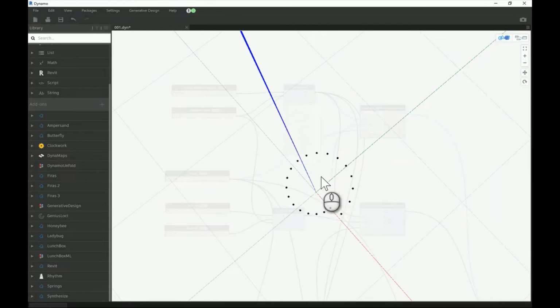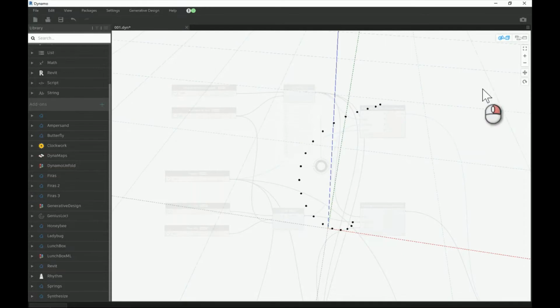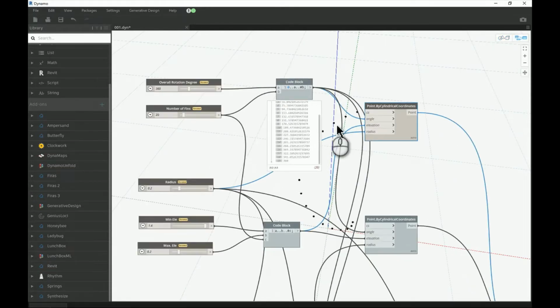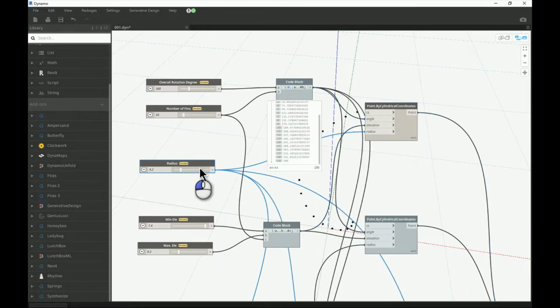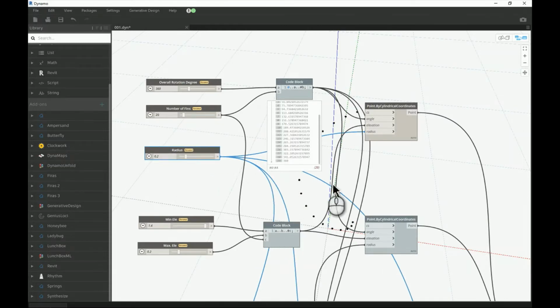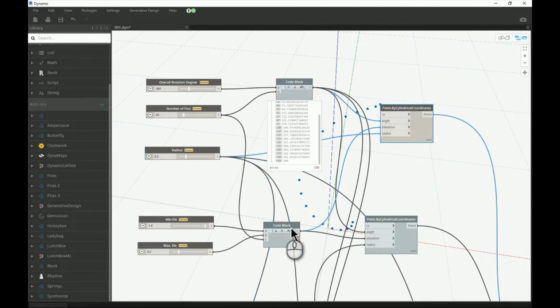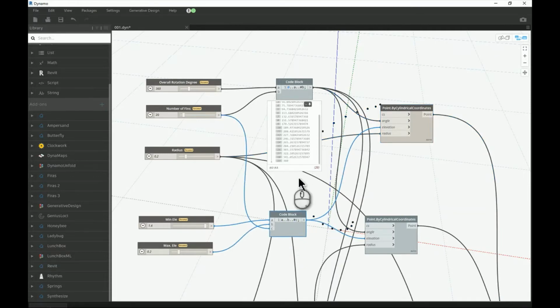Now the other things to specify for that spiral or helix, whatever you want to call it, are the elevation and the radius of it. The radius is fixed here, not changed, set to 0.2 for all the points at the same value. That's a fixed value here and not a range. And the elevation is actually changing to provide this spiral shape. Again, it starts from A, which I didn't set to 0, so you get more options. If you put 0 like what you've done, you're going to start from 0, but you're going to have less options.